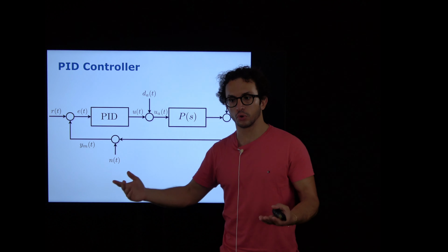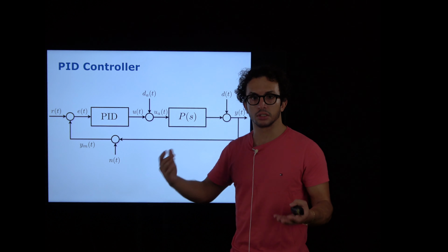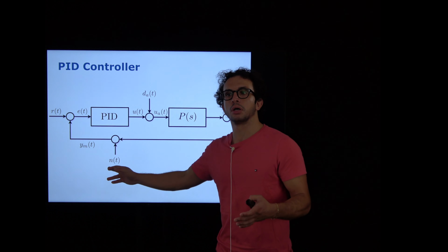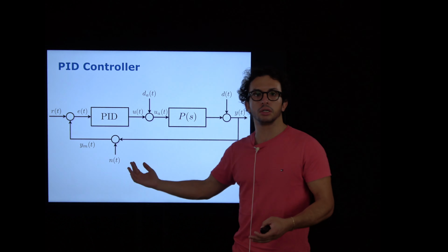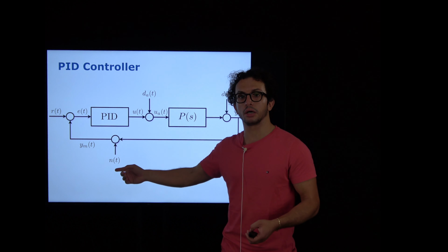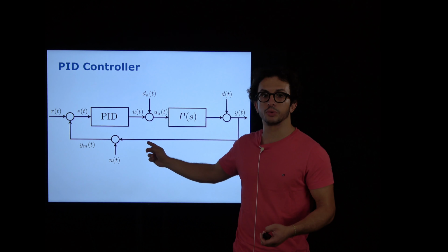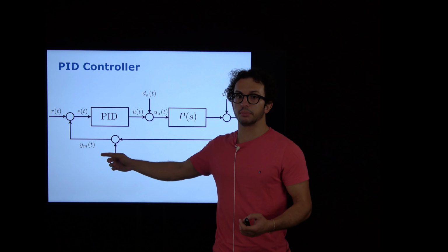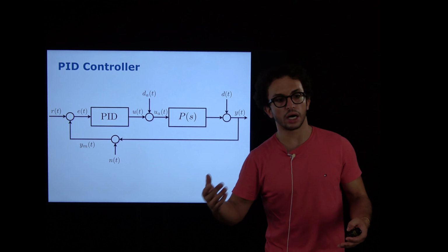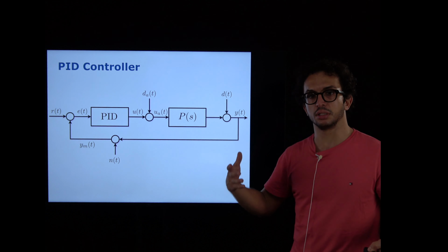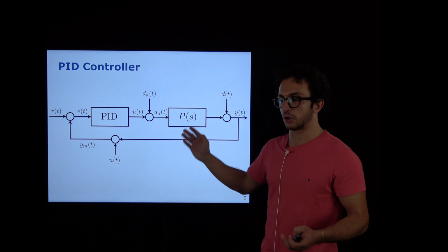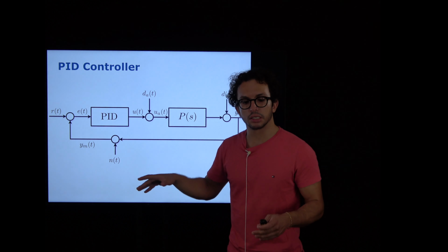And the sensor also, exactly as the actuator, is not perfect. The sensor could technically have some inaccuracies, can be not the best sensor out there, and so there's some sensor noise here that acts on the real output of the system to modify it a bit. This is YM now. It's not just Y, the output of the system, but it's a Y measured. So it's the measured output, which might be slightly different from the actual output of the system. So now this is the most